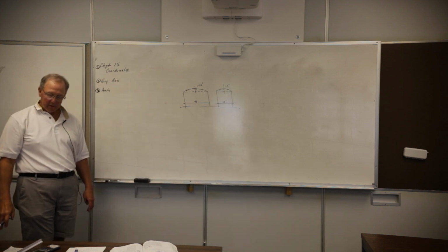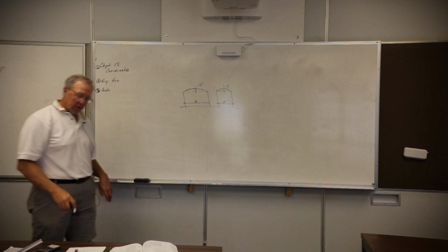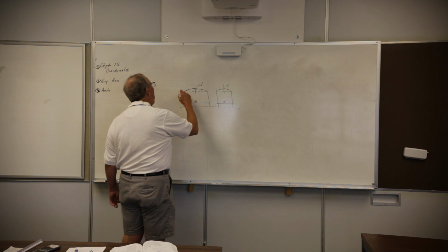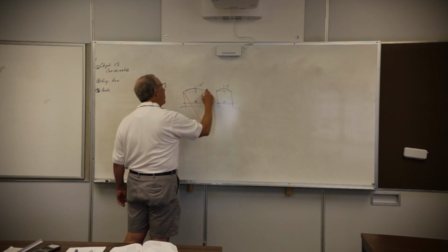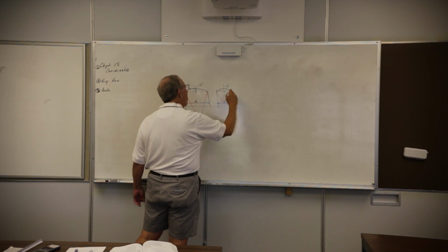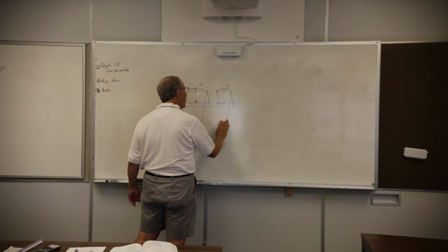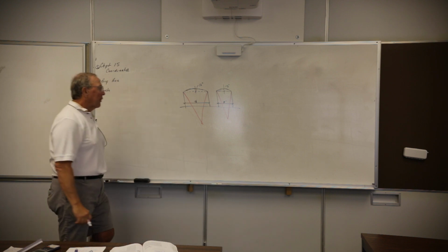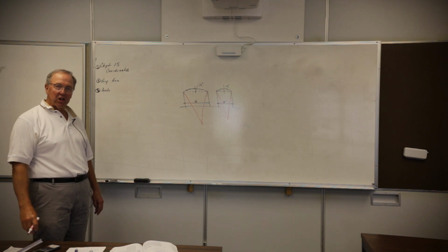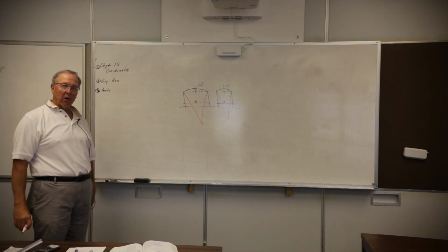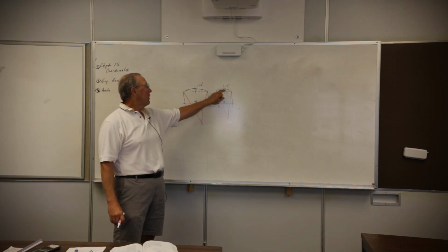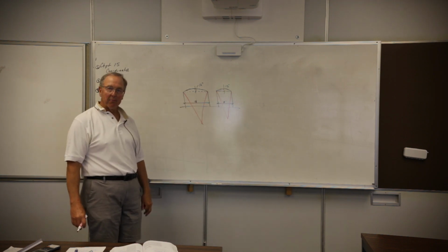Okay? Okay, so what I'm asking you to do and what the project would ask you to do is, what radius do I swing for those 2 guys so that when I get done, I have an 18-foot wide arch that has a rise of 12 inches in the middle for this one, and a 9-foot wide arch with 12 inches in the middle for that one.